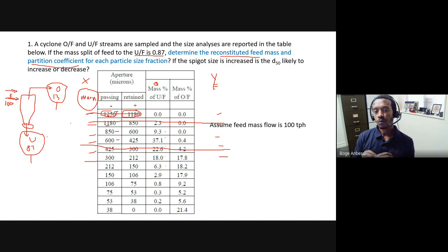the way a cyclone works is that it is basically closed. Whatever goes to the cyclone goes in a pipe. Basically, you are pumping the pulp through a pipe. Unless, of course, there is a leakage inside the cyclone. If there is a leakage, it's not going to work properly, because as I said, there is a very high pressure inside the cyclone. If you have a crack, you should be able to visually see it on the cyclone, and you shouldn't operate that cyclone.